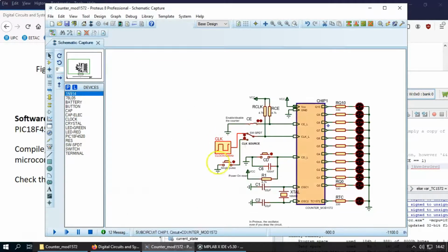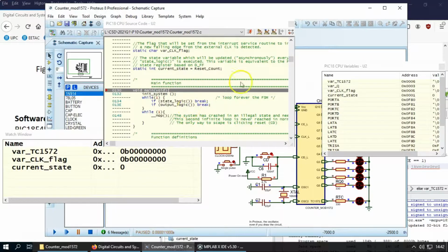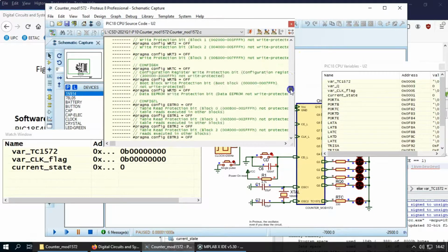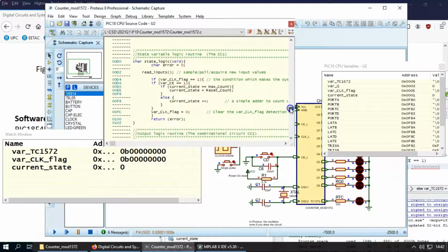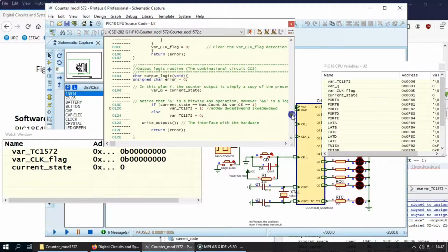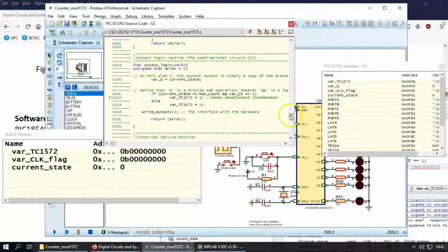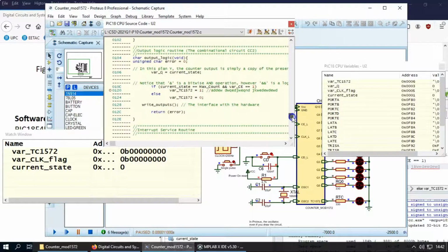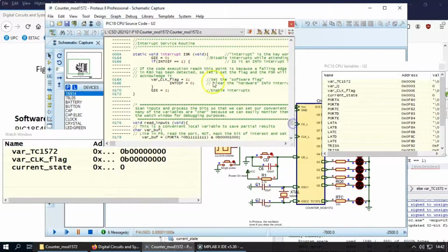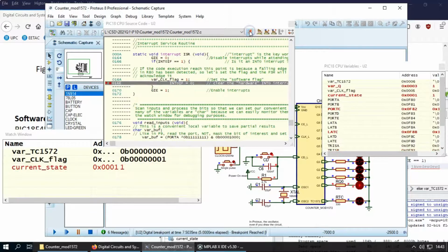Do you remember? Well, you have to go step by step now, and you have to find the interrupt service routine, because this is what you would like to monitor now: if the system is ticking at the right pace, established by the interrupt service routine. So here it is. Okay, if we click a breakpoint at this location and you run,